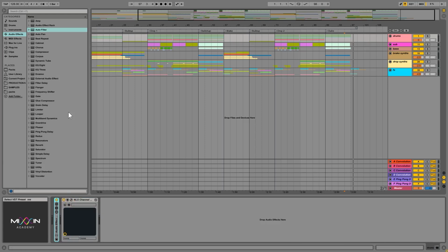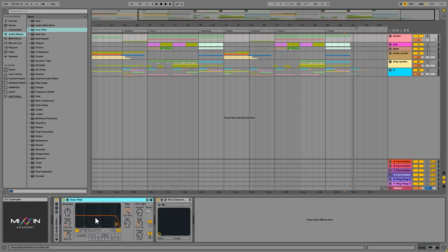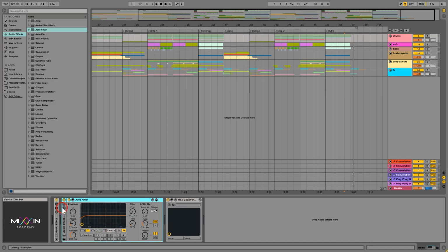Also, what I can also do is apply another kind of filter. So that was the low pass filter. Now I can apply a high pass filter, which I'm going to use in the same actual way. Meaning that I'm going to create that same group, you see right there. So I'm going to group this. So right click, select group, or just Control G, of course. And then I can do the same thing.